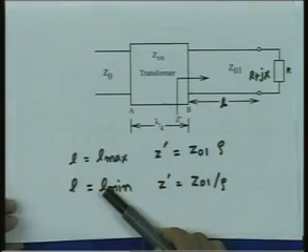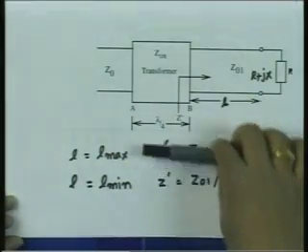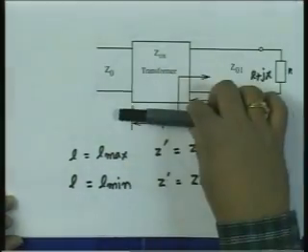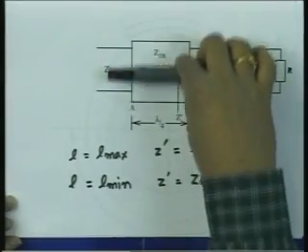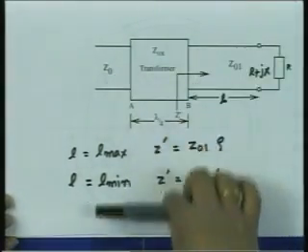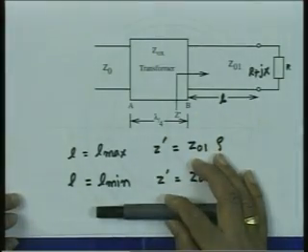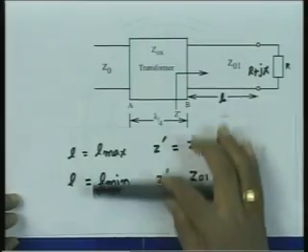Any solution is acceptable depending upon whether you want a shorter or larger length, and whether the transformed impedance you get can give you a realizable transforming line. One may choose one solution over the other, but theoretically there is no difference between the two solutions, and both are equally acceptable.